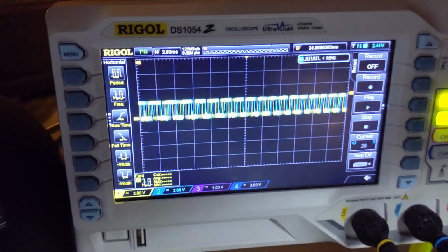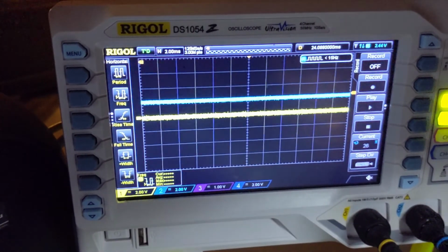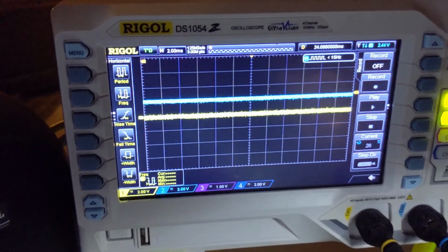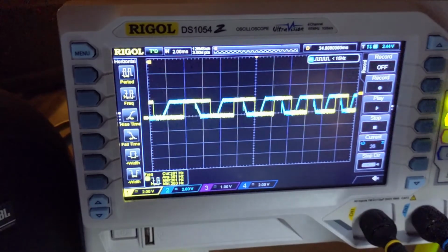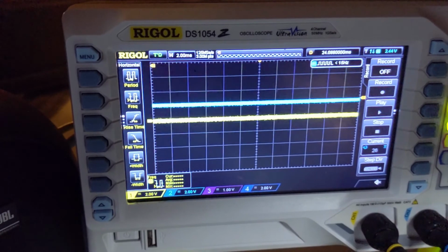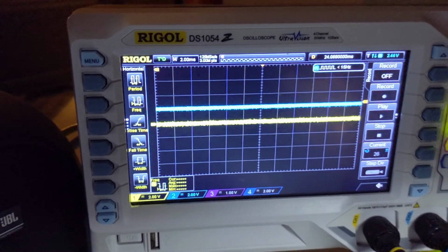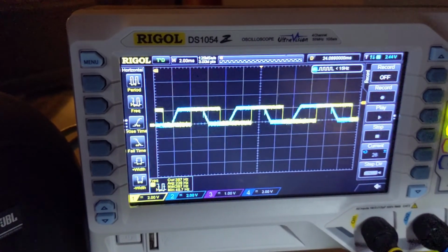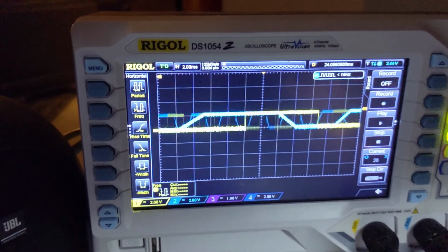And when you actually have the pure sine wave and you do the interpolation, you have to use an inverse tangent function to do that, which is kind of math intensive. But that allows you to get even more, up to, right now it's 14,400 clicks per revolution of position information, and that's 4 per pulse essentially.